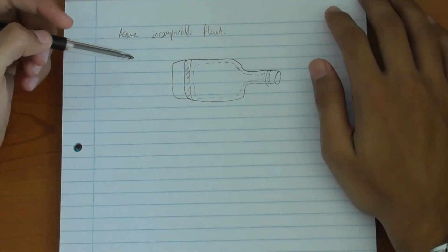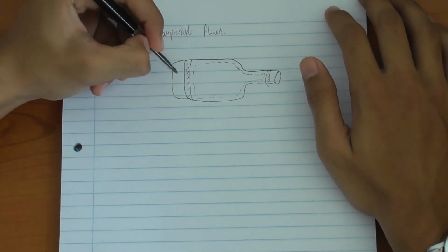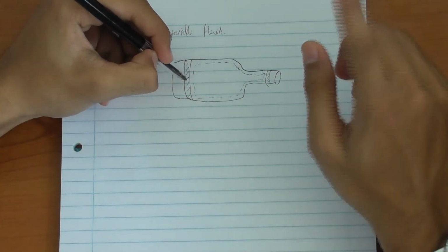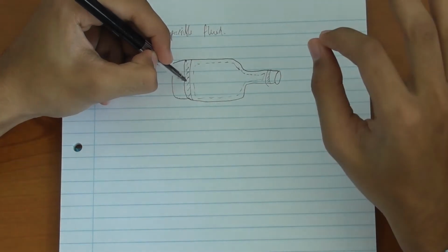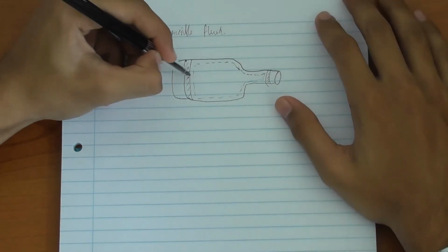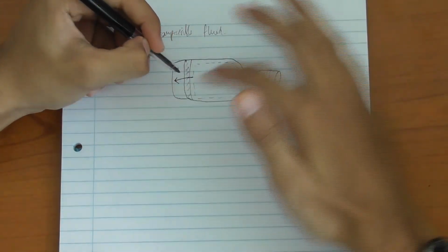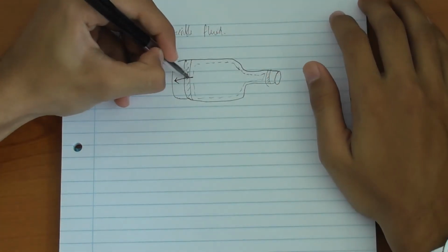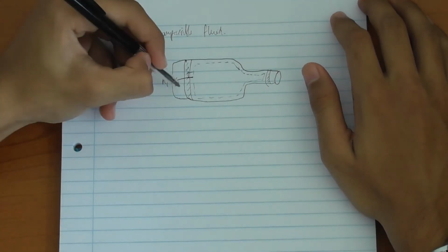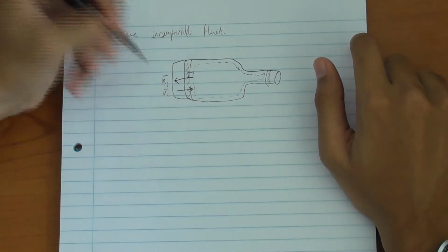So once you have selected your control volume, the next thing you want to do is set up your vectors. So I'm going to put down the velocity and normal vectors. On this control volume, the important thing to remember is that your normal vector always points outwards and away from the control volume. So outwards, away from, and perpendicular to. So we have something pointing outwards. Okay, it's perpendicular and away from the control volume. I'm going to label this N1 and put a bar on top to indicate that it's a vector. And we know that the flow of liquid is into the control volume. So I'm going to put V1.